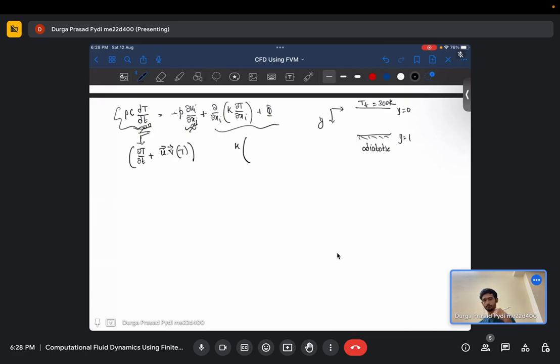Previously we neglected the phi term. Say you have a fully developed flow, where I shouldn't say fully developed, but let's consider that as far as velocity is concerned, it is fully developed, so you don't have del u/del x terms. It is also thermally developed, say, and the conduction along the x direction is negligible compared to along the y direction.